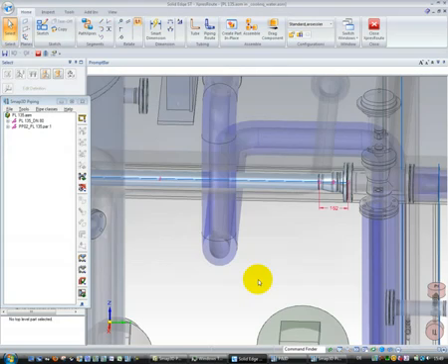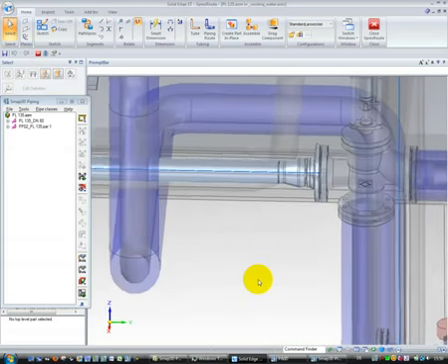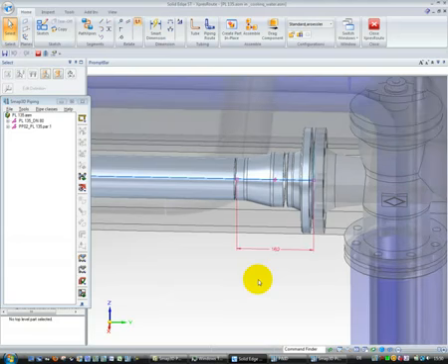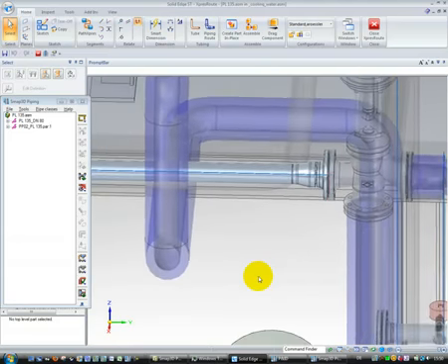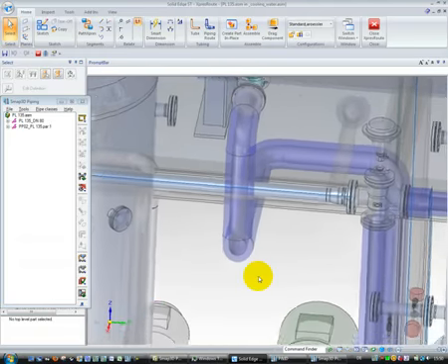When the software has finished all the processes and all the automations, we can see the result of our expanding or reducing process. During this process, there was a message about non-unique fittings, where I have to define which kind of fitting I would like to use for the same situation. In my case, I use the favorite because I just clicked on OK without a specific selection. So now we have reproduced the correct situation in the pipeline.